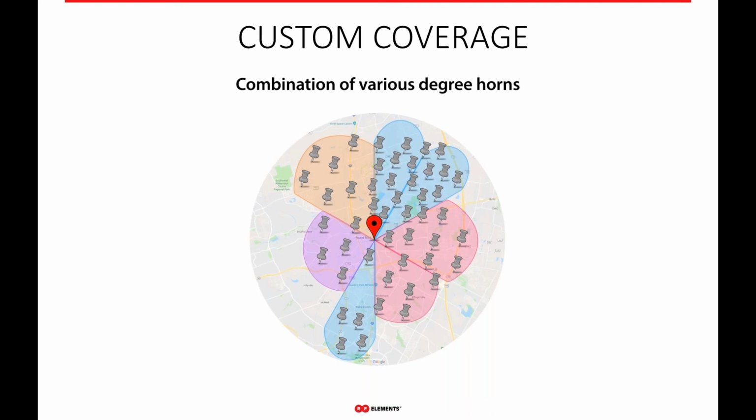So this, again, allows you the ability to use not only the resolution of the width of the horn, but also, as we talked about understanding your technology, you could also use narrower horns and effectively give them less gain by utilizing down tilt to paint the coverage of your area. This really helps you become spectrally efficient, because traditional sectors have so much gain, and their beam patterns are so uncontrollable or so wide.